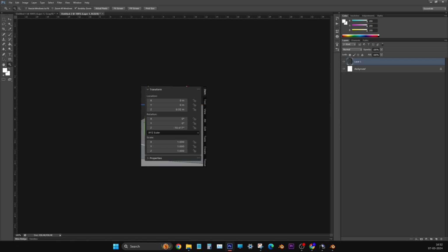Now go to perspective and turn around the camera and see, you will have an idea what you have done. It is a bit away from the world origin. Now we have to bring this pivot back to the world origin. For that again, Control A, all transforms. You have to select that object.